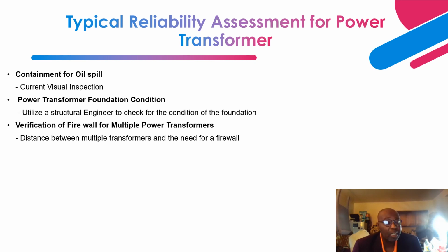Next is the foundation. Here also you need a structural engineer to assess the foundation, because as a power transformer sits on the foundation for 40, 50 years, sometimes cracks develop in it. And as you know, these transformers are very massive, with a lot of weight from the active component and oil. To continuously support that weight, you need a resilient foundation, one that won't be compromised with cracks, right? That's why you need that assessment to be done by a structural engineer.